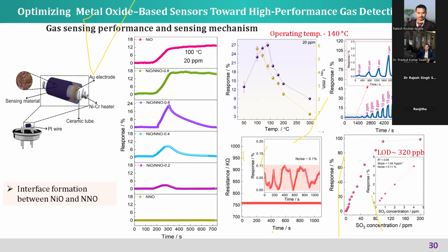And again, coming to humidity, it is one of the important parameters. As I told you, when you have more humidity, more hydrocarbons are going to form on your sensor surface. Then accordingly the response is going to decrease. So we always do a controlled humidity study for these things. But when it comes to the sensing platform, we have a humidity sensor installed in the sensor itself.